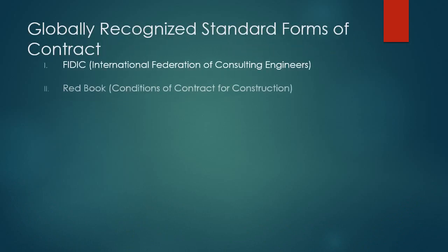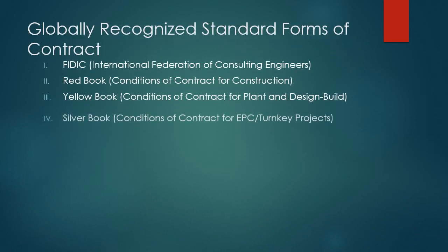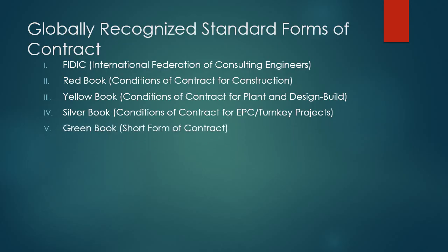Globally recognized standard form of contract. Number 1, FIDIC, International Federation of Consulting Engineers. Red Book, Condition of Contract for Construction. Yellow Book, Condition of Contract for Plant and Design Build. Silver Book, Condition of Contract for EPC Turnkey Projects. Green Book, Short form of contract.